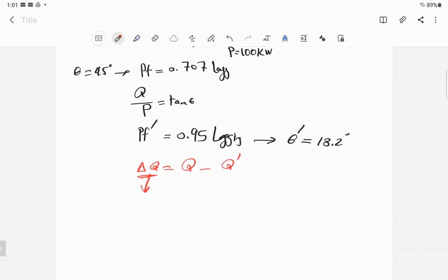How can you find the value of C, or XC at least? How can we find XC? Well, we know that Q can be found by V squared over X. So if you are looking for Q delivered by C, it's V squared divided by XC. So if you know the QC, which is the old Q minus the new Q, when you subtract, that's QC. And the voltage is the voltage of the system and the load. If the load takes 120 volt, it's the same thing on the capacitor, because you connect the capacitor in parallel. Then you can find XC.